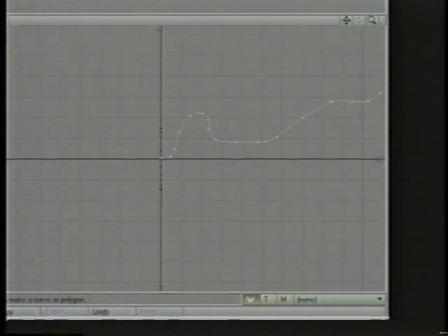So I'm going to select layer 2 as my foreground layer, and I'm going to go ahead and select layer 1 as my background layer so I can see where my disk is in relationship to what I'm about to create. So I'm going to create a curve that goes off in this direction. So I'm going to say sketch, start sketching out just a kind of a path for this rail extrude to follow. So this is my rail, and I'm going to extrude this disc along that rail.